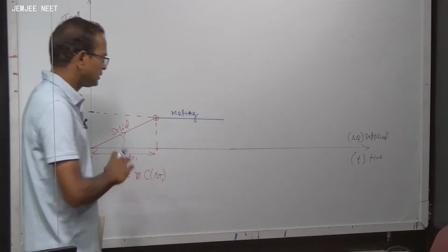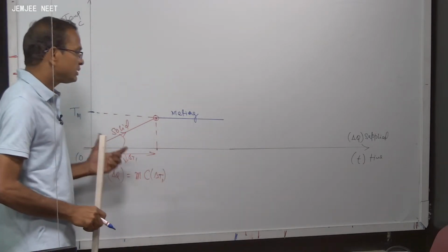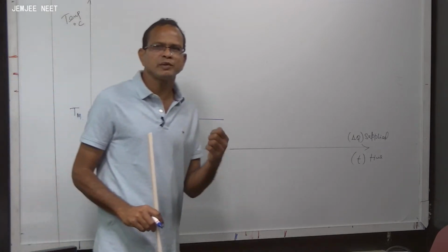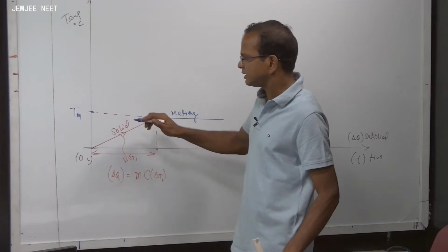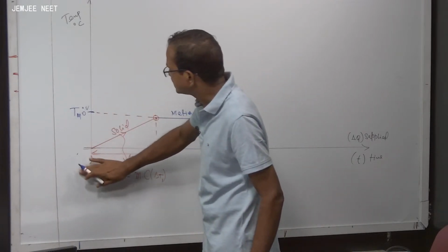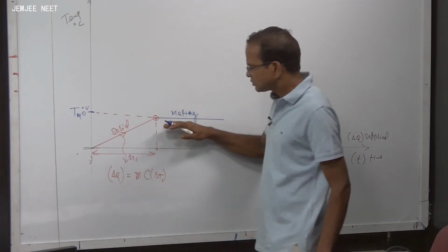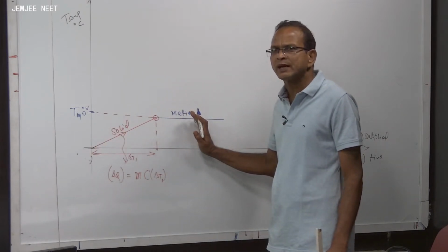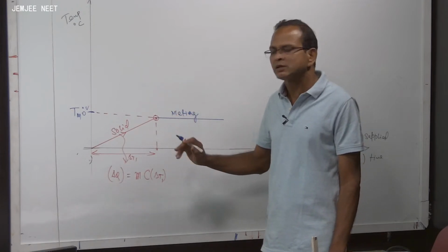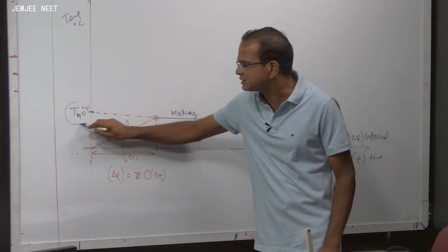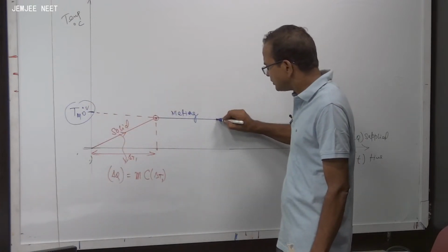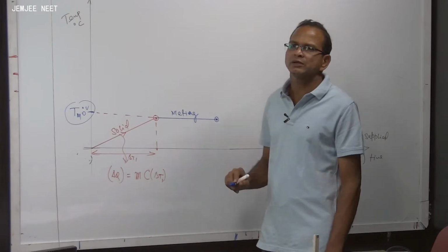Temperature of melting started. Now will your temperature increase? No. Now your ice started melting. In your container there is 50% ice and 50% water, but your thermometer still reads 0 degrees Celsius. When 75% of the ice has melted and 25% remains, your thermometer still reads 0 degrees Celsius. Here 100% of the ice has melted, everything converted into water.